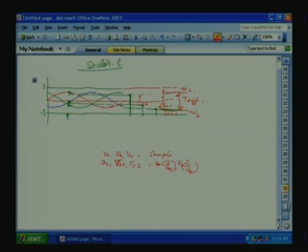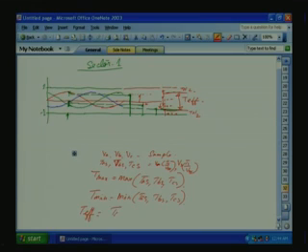Now, if you see here, the T effective period is between the maximum of the sampled value and the minimum of the sampled value. Minimum here is negative, maximum is positive. So, you find out T maximum. T maximum is equal to the maximum of TAS, TBS and TCS. Then you find out T minimum, that is the minimum of TAS, TBS, TCS. Then what is the T effective in sector 1? T effective is equal to T maximum minus T minimum. T effective we have found out.